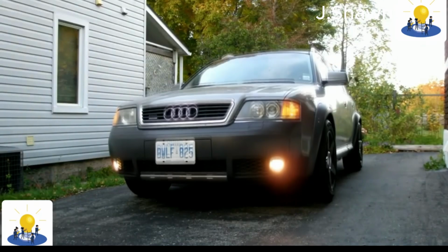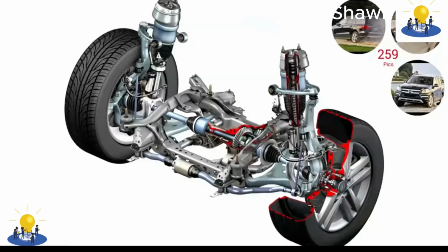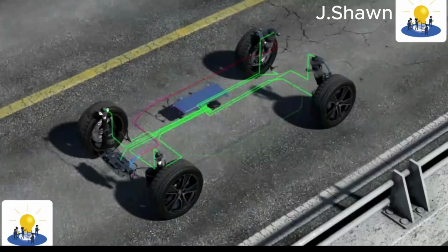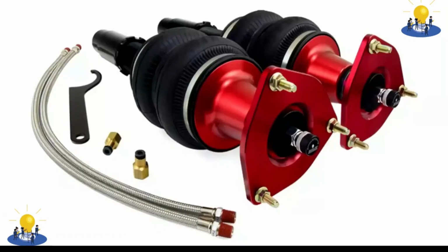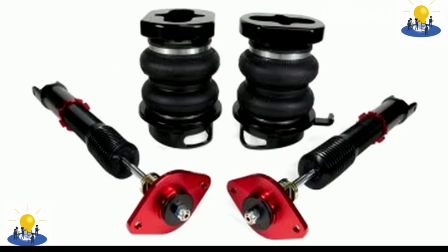Air suspension is a type of vehicle suspension powered by an electric or engine-driven air pump or compressor. This compressor pumps the air into a flexible bellows, usually made from textile-reinforced rubber. Unlike hydropneumatic suspension, which offers many similar features, air suspension does not use pressurized liquid, but pressurized air. The air pressure inflates the bellows and raises the chassis from the axle.